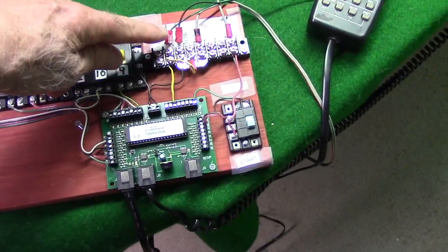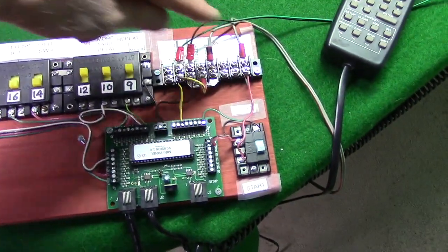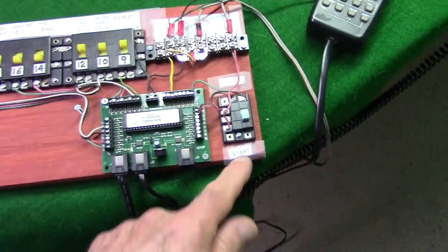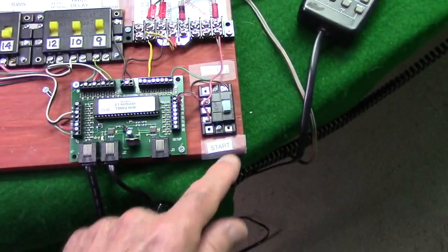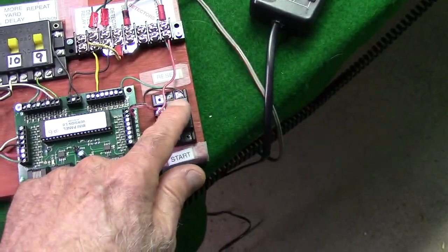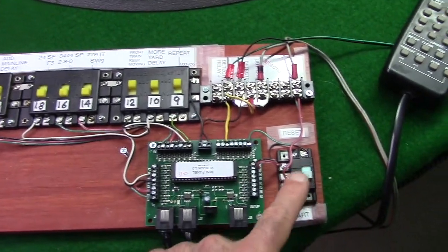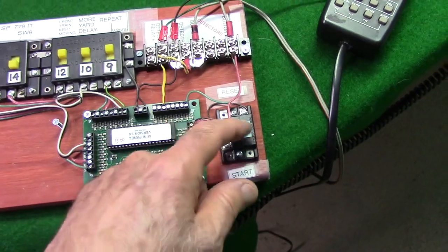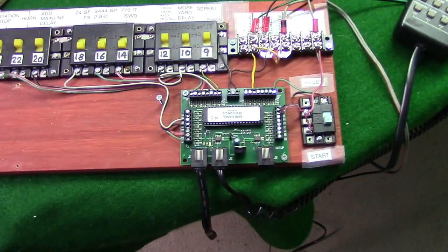If the input's not grounded, have it do something else. And here's our connections, just 2 of them. This is the terminal 1 where the push buttons are connected to start things, and this is terminal 6, I think it is, where the detector is connected. Then this is an Atlas number 56 momentary switch, and we use the 1 position to start things. This button does the same thing as this button over here. You push it down momentarily, and it grounds input 1, which starts things up. And then if we push it over here and push it down, it connects to the reset terminal. It resets the mini panel. That's like a hard stop if you need to do that.